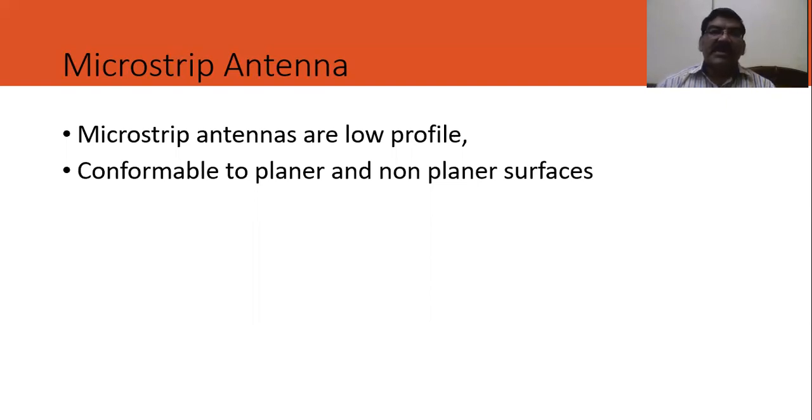There are around 70 antennas. Maybe in a domestic aircraft a little less, but in a fighter plane there are more. Most of these antennas are microstrip antennas, because the surface of the plane is important because it affects the aerodynamic property. So it is conformable, but it is a planar structure.